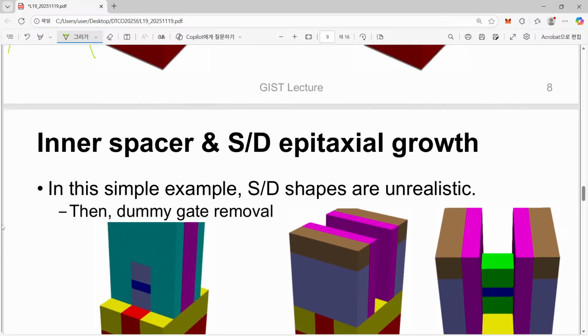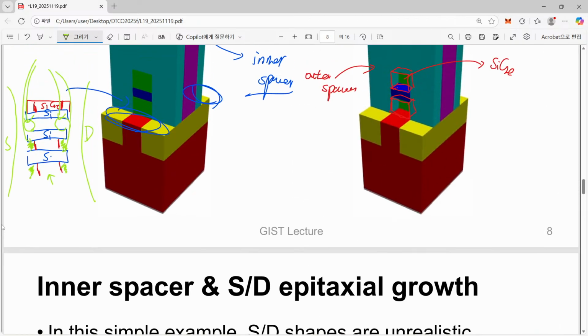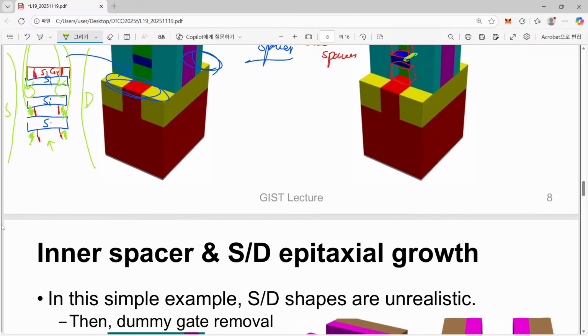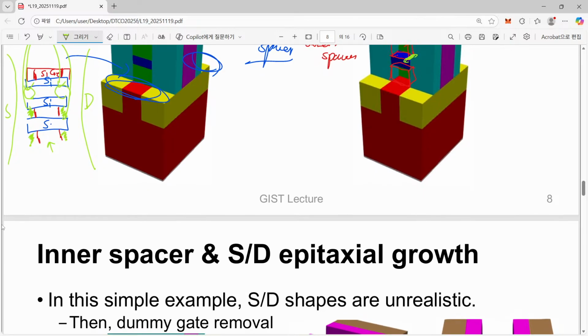After that, now we have etched some portion of silicon germanium, and how deep is this inner spacer etching? That is really important, because it determines the distance between source and gate and the distance between gate and drain. That is determined by this difference. Its control is important. And how can you generate this distance? Just by etching our silicon germanium.